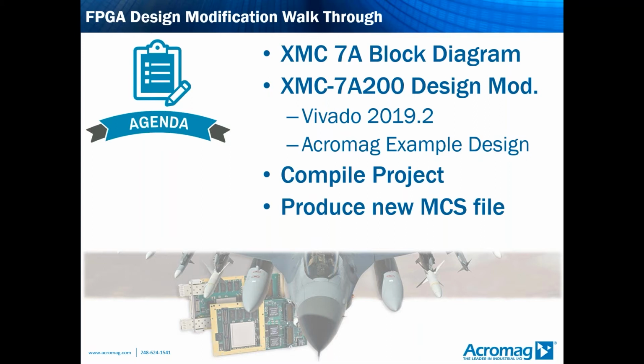We're going to be using Vivado 2019.2. I have the webpack, that's the free edition. So for the 7A, the free edition works really well. If you're going to be doing a modification for the 7K series, the webpack is not going to be very useful, since the actual FPGA chip used is supported in the HLX edition. So we're going to be doing a modification to the example design that we provide, followed by compiling the project and producing the new MCS file.